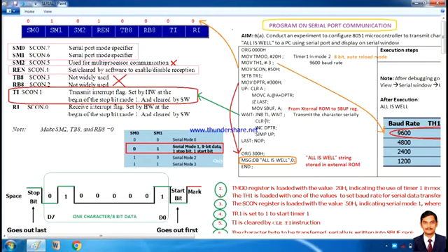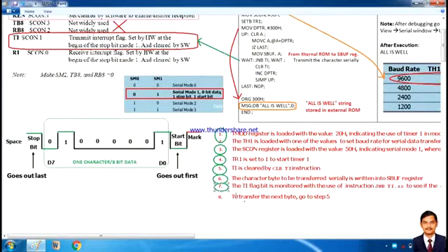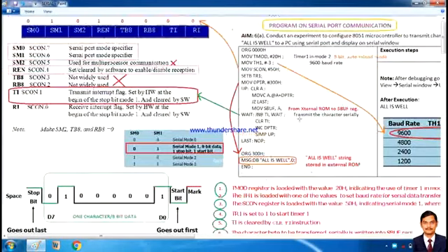I am using this instruction to ensure that the next character is yet to be sent, so I am clearing TI. So in this way we monitor with JNB, an instruction very helpful in transmitting the data character by character. The A will be sent first. As soon as it recognizes the stop bit, it comes over here, clears TI, and increments DPTR.